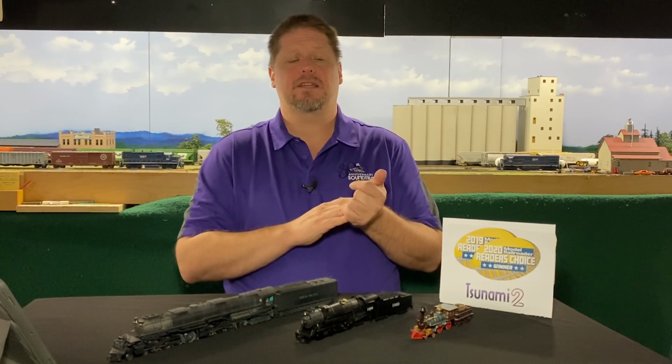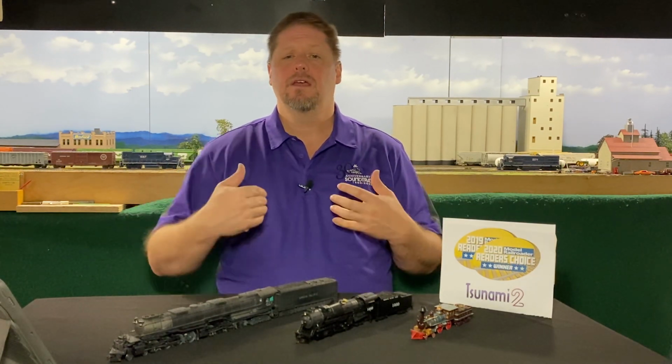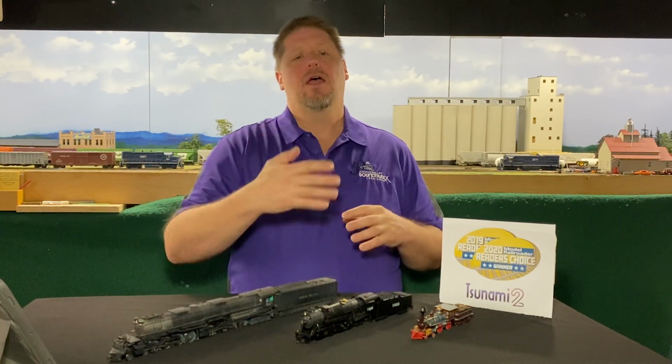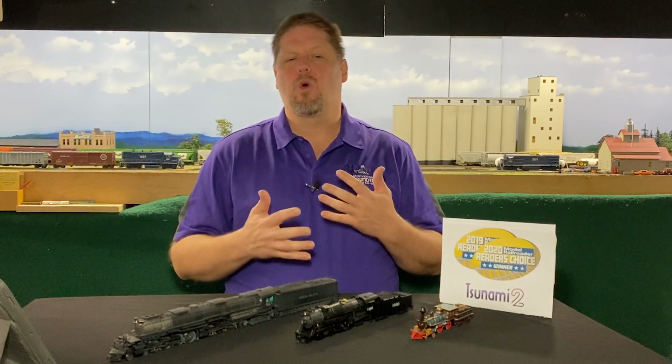the commanded speed step. So for example, at speed step 20, you might get, we'll say, 1.2 chuffs per second. Now, what happens is when you're running uphill with a heavy train, your locomotive may physically slow down and not quite go as fast. Well, there was no interaction between the motor and the commanded speed step, and so therefore the chuff rate continued at a higher rate even though your locomotive was slowing down. It created a very poor illusion of what we were trying to create.